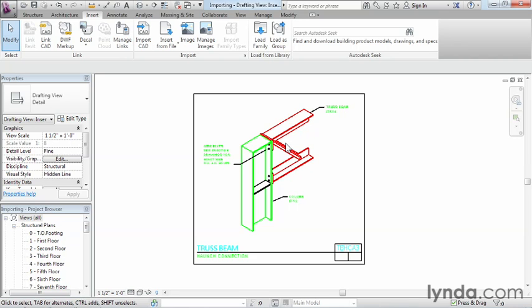It's also going to make it a little bit slower for Revit to process the model as you're spinning and doing different things. So as a result of that, I usually don't recommend just coming in and using the pure import and then explode on these entities to make modifications to them. Instead, I usually recommend doing linking, which we'll be talking about in another video in this section, because by linking them in instead of exploding, we can make drawings and changes a little bit quicker and cleaner than by using the import CAD method.